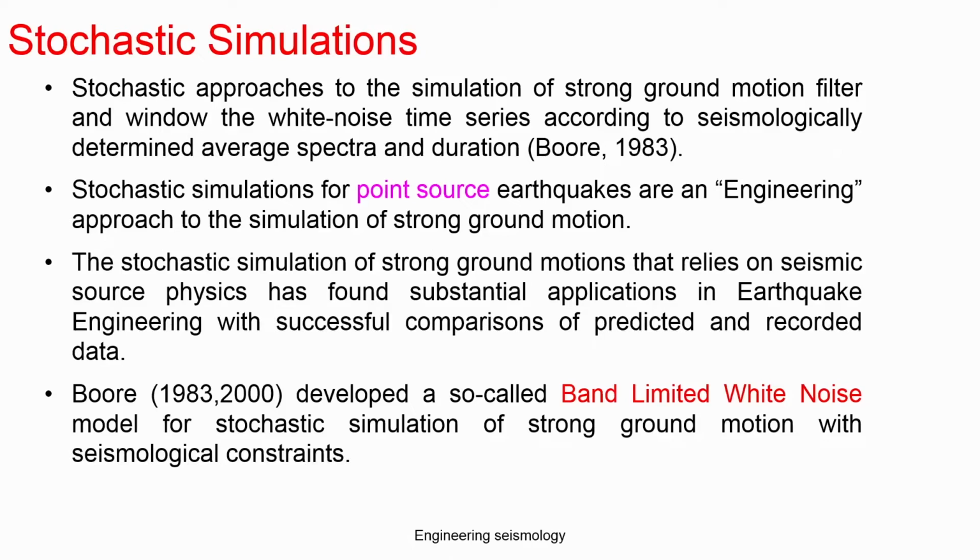So, the stochastic simulation approach is the simulation of ground motion by filtering windowed white noise time series according to the seismological determination of average spectrum and duration. The stochastic simulation point source model. Okay. So, this is an earthquake engineering approach to simulation of ground motion, which was developed by Boore in 1983.